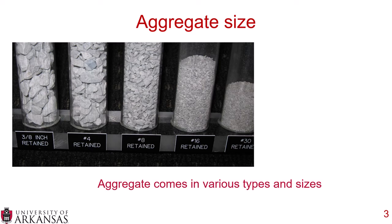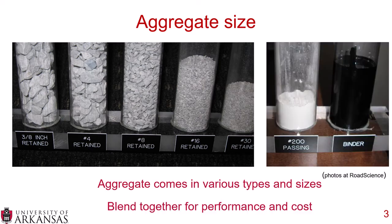As you can see, when you're going from the left to right, the aggregate sizes get smaller. As you go down even further, you get to passing the number 200 sieve, and then it's all put together by asphalt binder. You need to take these different sizes of aggregates and also different sources of aggregates and blend them together, trying to balance both performance and cost.